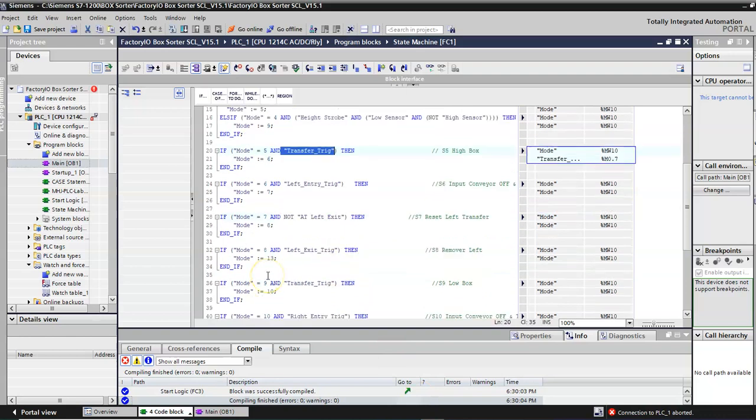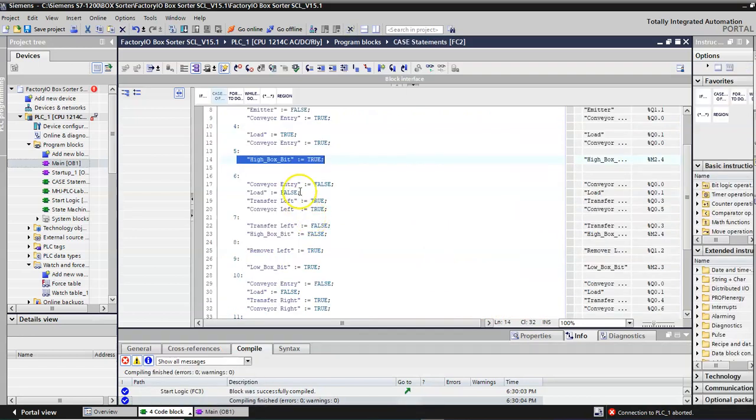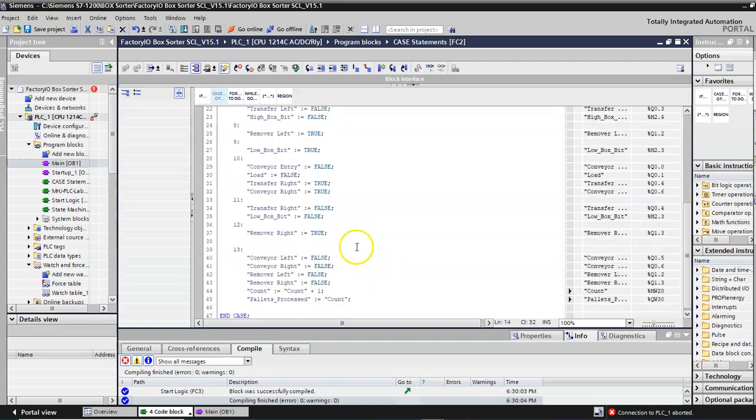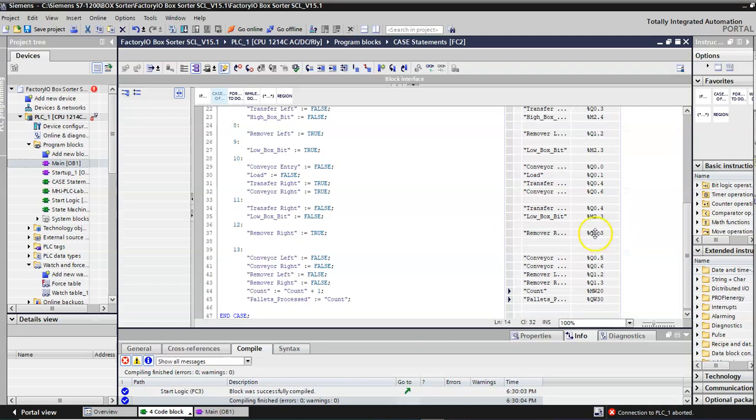What you're doing in each of the steps is governed by what step you're on, and you're just telling things to turn on or turn off. True is active, is on, false is deactivated, or logic 0. So we're just saying these are true or these are false, and we're walking all the way through with that. And it's not anything visual. It's a lot harder to try to troubleshoot. But you can, and so we'll take a look at what you can do.